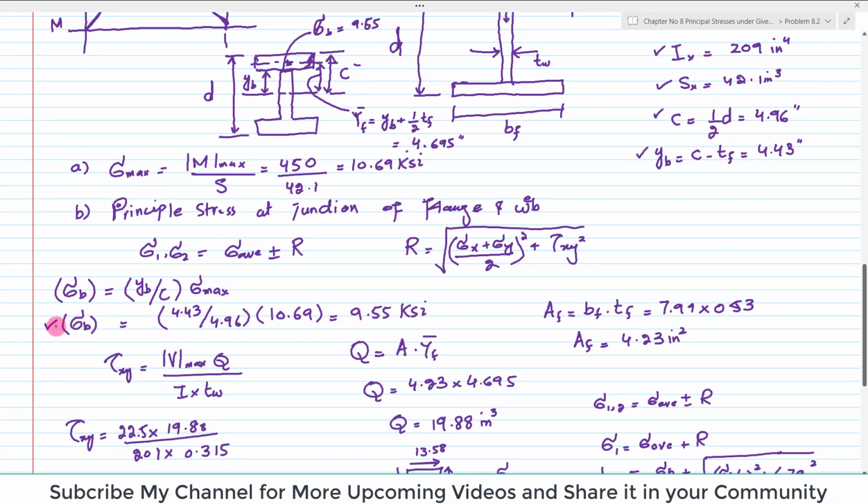Now you have this normal stress, and we know that we need the shear stress at this junction point as well. So the formula for shear stress is V max Q divided by I times the thickness of the web. We have V max from the shear force diagram. We do not have Q. We have I, the second moment of inertia, given in the properties. We have the thickness of the web.